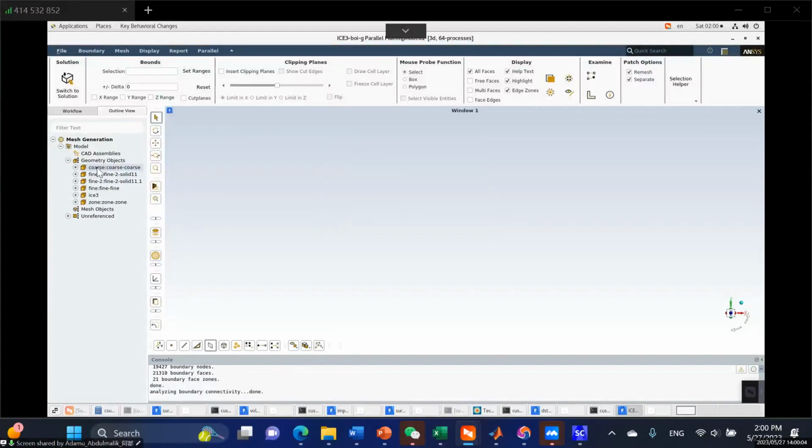The size field is just like you put in values, because Ansys Fluent Meshing is an automatic meshing, so you are not going to generate this mesh yourself. You are going to input numbers, values on various parts of the train that you have already grouped, you have already named.